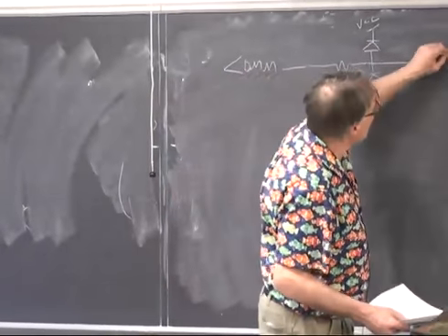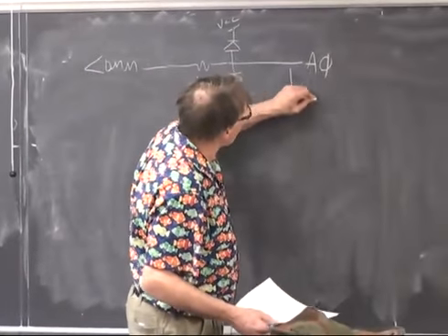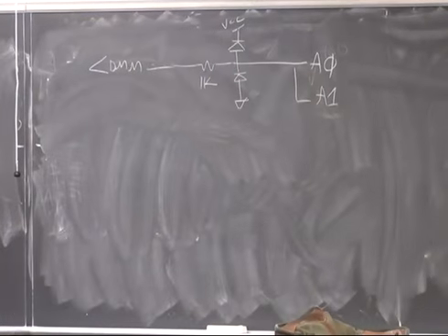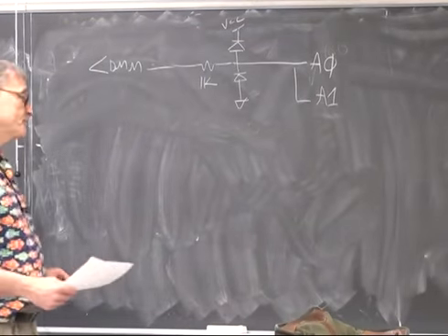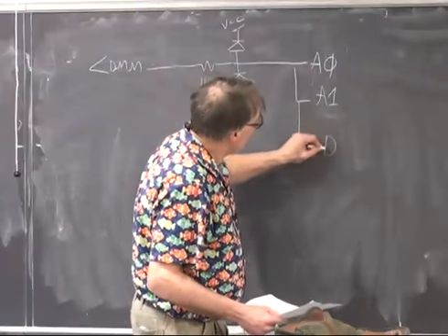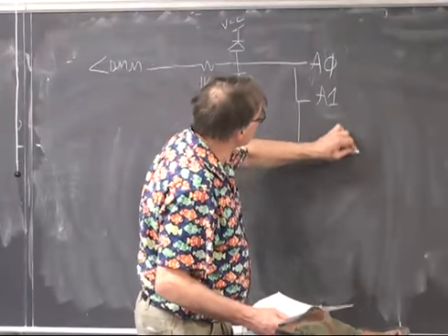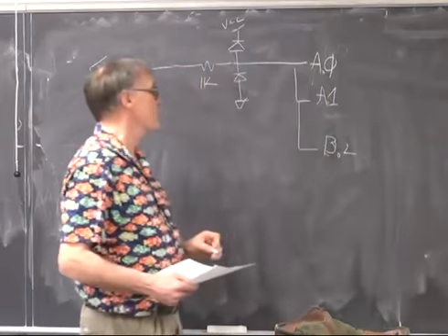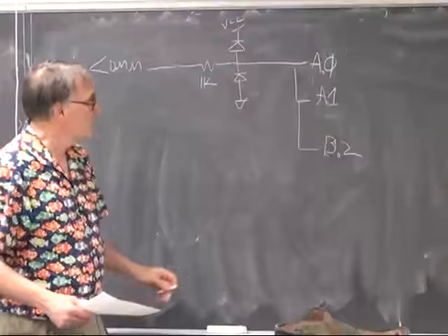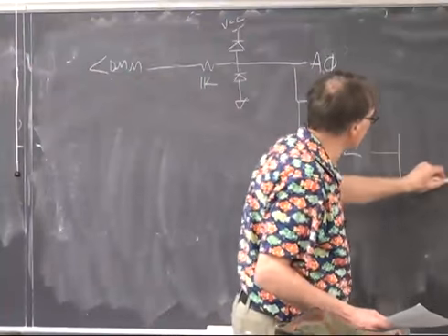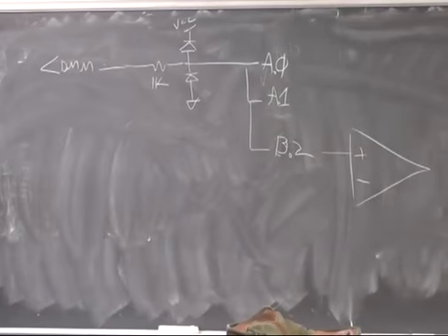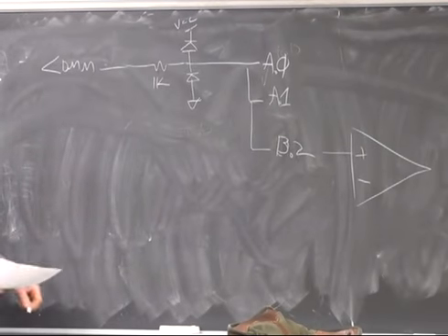This is then going to go into one or more channels of the A to D converter, A.0 and A.1, and also to port B.2, which is internally connected to a comparator. We're going to talk more about how the comparator is connected to timer 1 in a few minutes.